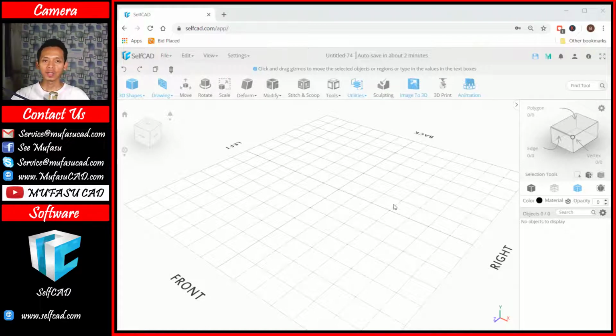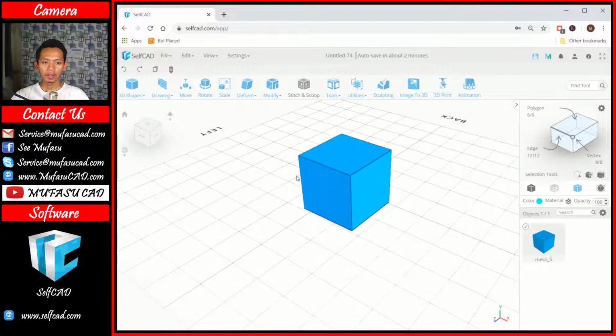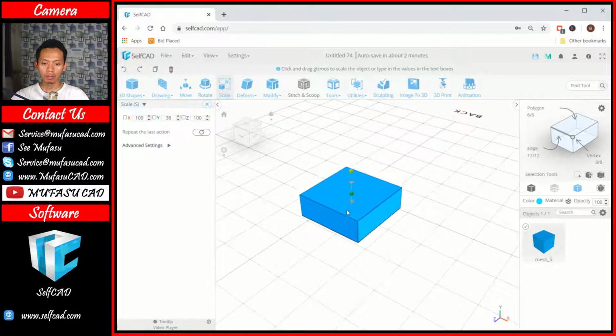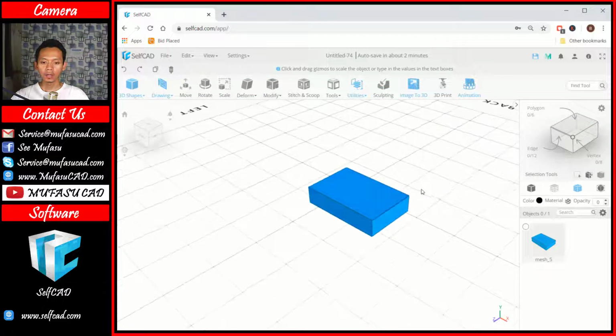Today I will create a 3D low poly car. First I will insert a cube object into this point, and then we can use the scale command to scale this box. Okay, I will move into here, then we scale again in the blue axis. Now in here I will use the polygon option. Select this object and we use polygon.